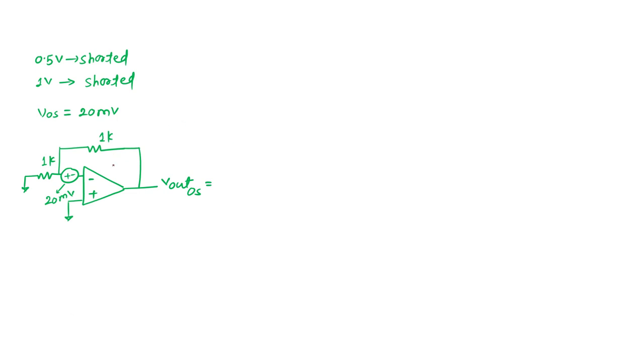Because we are seeing that it is an ideal op-amp, this node, from the virtual ground, will be zero. So the node connected to this amplifier will be zero. I can draw the circuit again here. This is my amplifier, and this is ground. So this node will also be ground. I should draw it some far away.